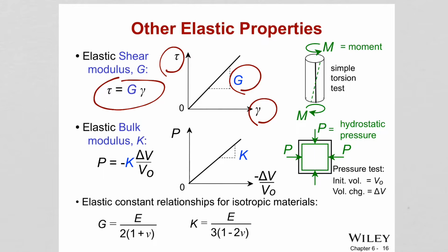All these modulus values depend on atomic bonding strength, and all of these follow Hooke's law, because it provides us a linear relationship between stress and strain. Besides that, we can correlate the moduli to each other. If you want to figure out one modulus but you know another, you can use the equations that correlate them, such as finding G from E, or K from E. To be able to do that, you need the Poisson's ratio.